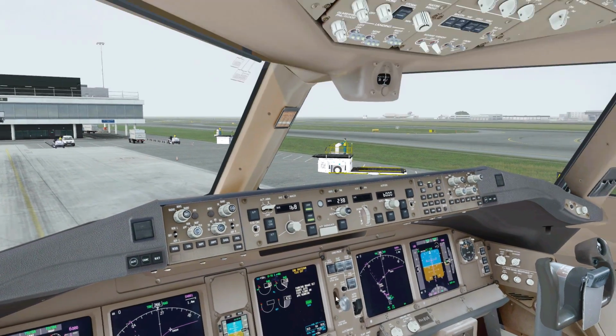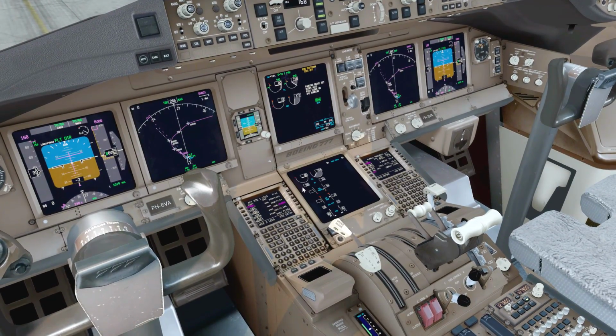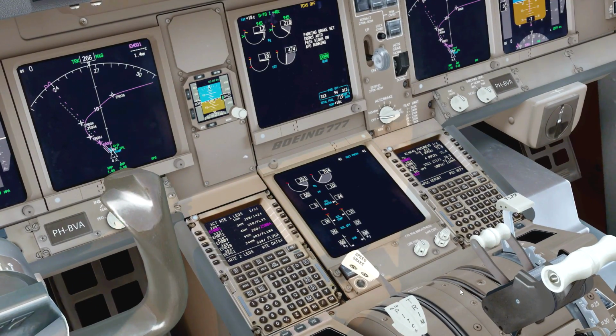It's been stabilized, so we now can continue ahead with the first engine again. Just put the engine start switch to start. As soon as you see some indications right here, you can put the fuel control to run. In the meantime, the ground crew is clearing up the pushback truck. Again, monitor the values. Make sure you keep your hand close to the fuel control switch, so in case something happens, you can abort it if the system doesn't do so itself. N2 rotation. We got N1 rotation coming up. So right about now, the fuel is going to be injected.